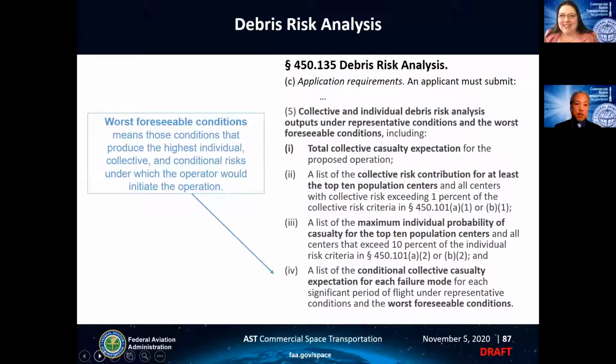According to section 7 of 401, effective casualty area means the aggregate casualty area of each piece of debris created by a vehicle failure at a particular point on its trajectory. And here it's noted that in reality, the probability of casualty decreases with the distance from an explosive impact, and the effective casualty area is a modeling construct, the area within which 100% of the population are assumed to be a casualty, and outside of which 100% of the population are assumed to be unhurt. Next slide, please.